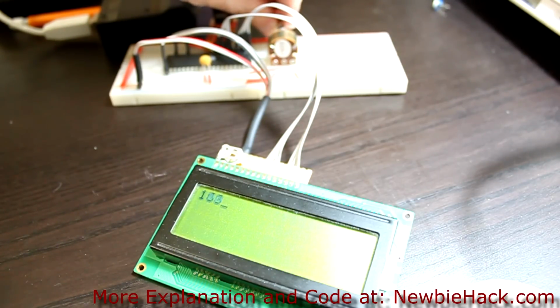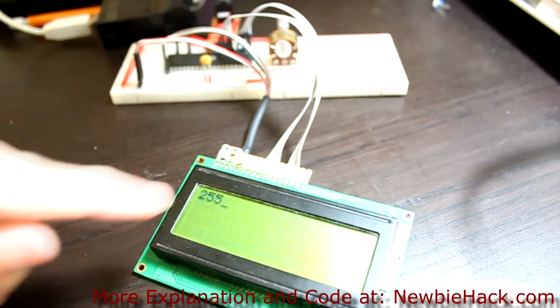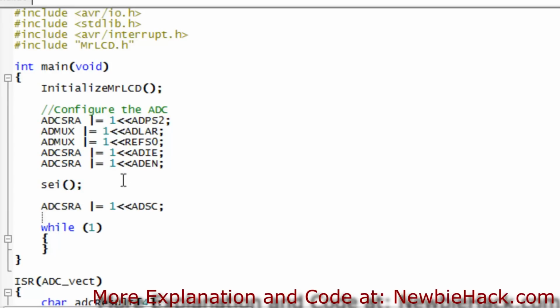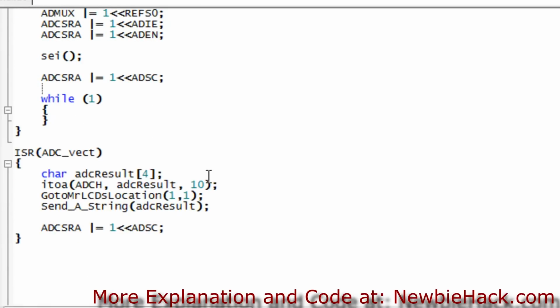I didn't erase the zeros that are after the number while it was counting down. So let's put in a little bit of code to make sure those zeros do not exist while it's counting down. All I'm going to do is add a space after the send a string. We're going to send another string, and we're just going to put a space in here, and this space will happen right after the number. So as the number goes down, there will be a space, and anything that was there will be erased. We're going to make and program this one and see the results.